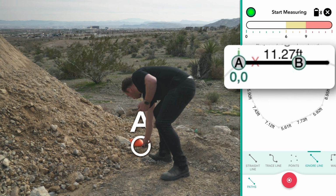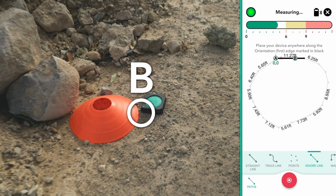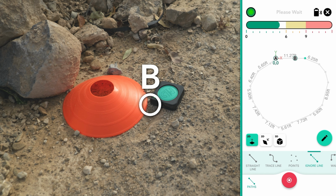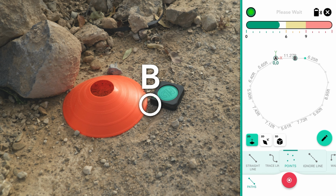A black guideline appears on screen to help you follow the same reference edge. Once the A to B reference walk is complete, the app switches to Ignore line, allowing movement within the perimeter without changing it. At point B, change the path type from Ignore line to Points. The Points path type allows you to place individual elevation points rather than following a continuous line. This creates a new reference point, point C, at the same location. This is the point you'll return to when finishing the layer.